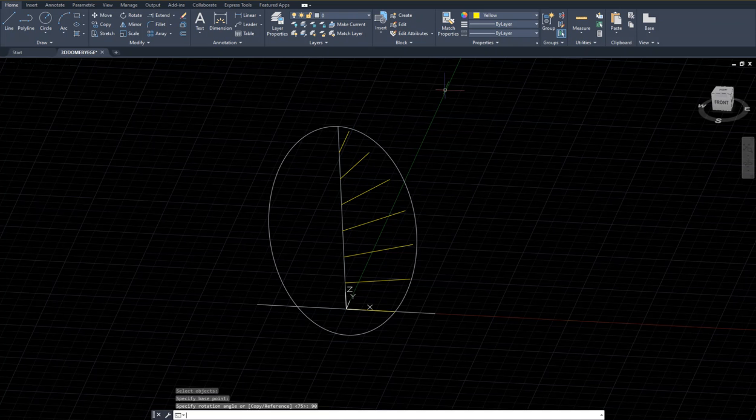And now I can generate a 3D polyline connecting from the end of the lines to the end of the lines. What's the 3D poly or spline command? These are the commands that enable you to generate three-dimensional lines. You can use the regular line command, but it is not going to work as nicely as a 3D poly. You can use 3D poly and it will work beautifully, but perhaps spline is the better command. So where do you find the spline? You can type it. You can definitely type it.